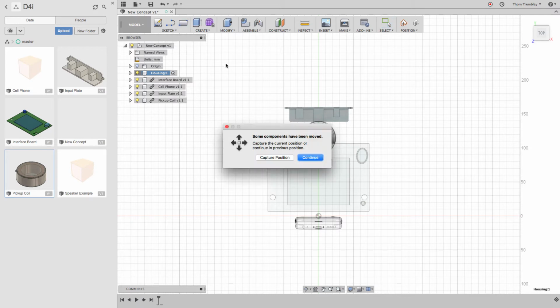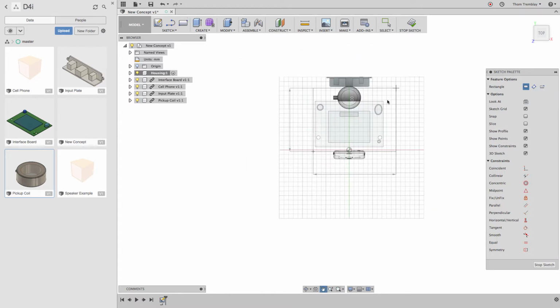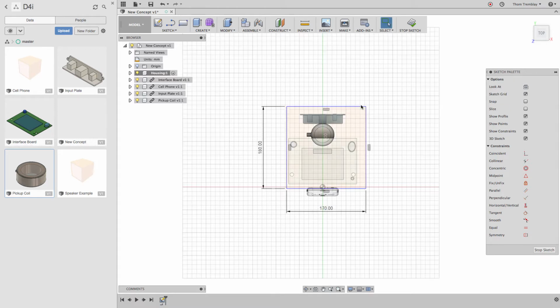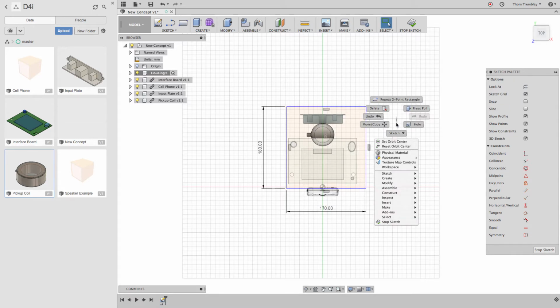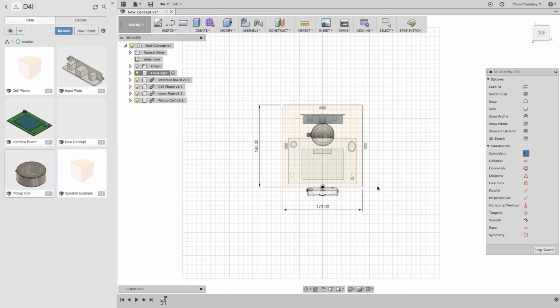My idea is to create a more vertical version of the Latitude consult system that integrates a phone base in the front. I'll start out by just creating a sketch. By including parametric dimensions in my sketch, I can quickly and easily modify the footprint of my design. I'm going to take a moment to align the rectangle to the origin of the sketch. I'll click the origin of the sketch, then holding Shift, be able to click the midpoint of the line.